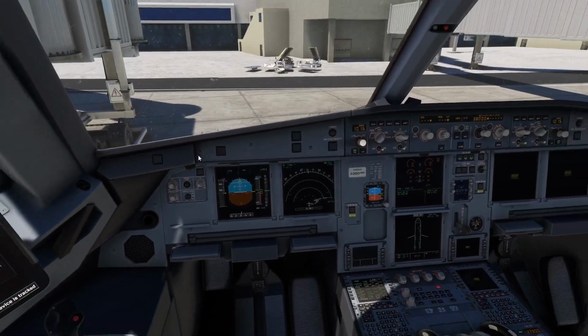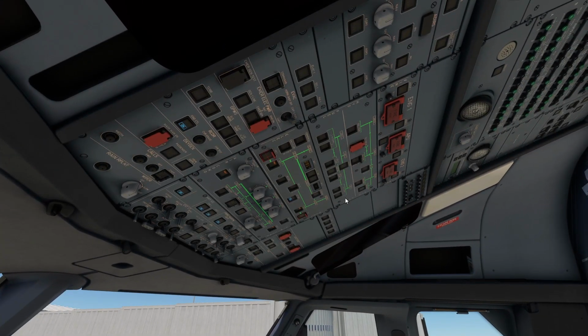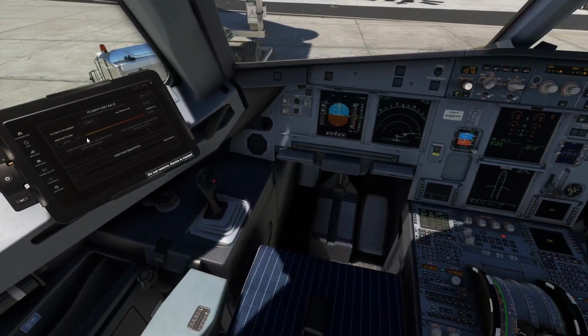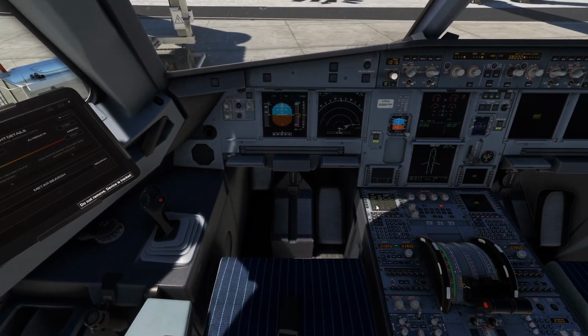Now all left to do is literally just set up the aircraft. So fuel, wings and anti-ice probes, APU, then APU bleed. So make sure these are the first 3 things you set. So power on, so put the batteries on, then put the external power. Once external power's on, set these 3, and then do your EFB, and then do your MCDU.